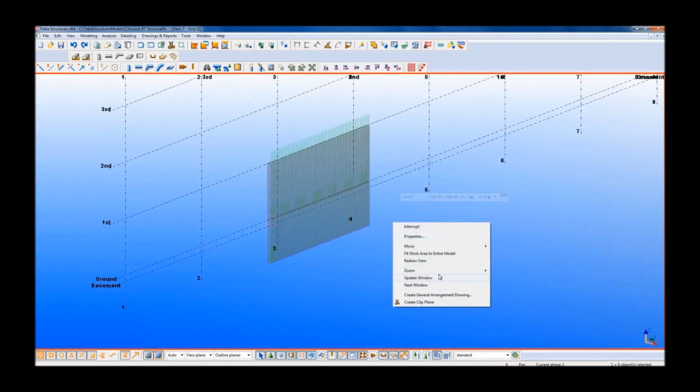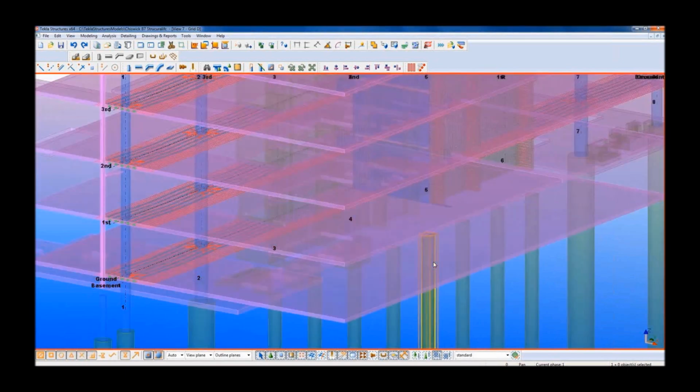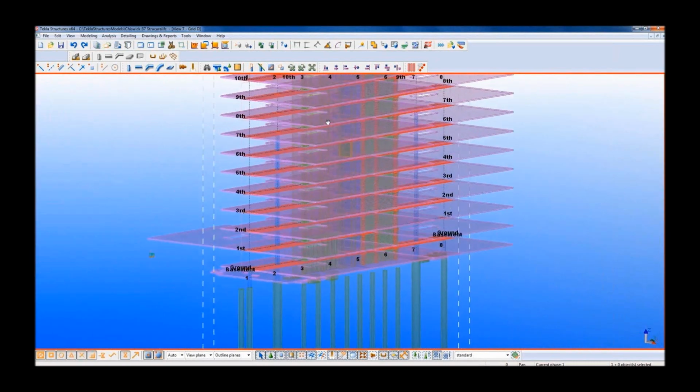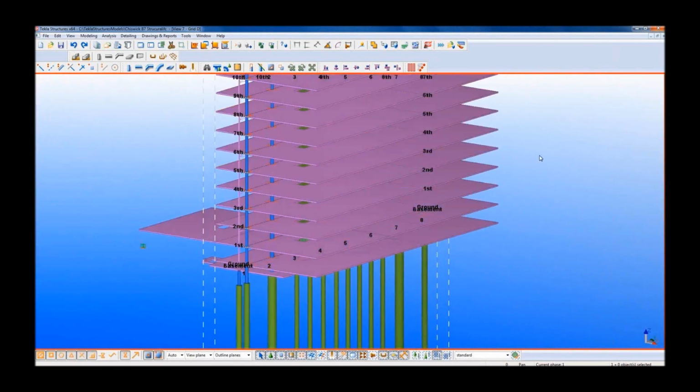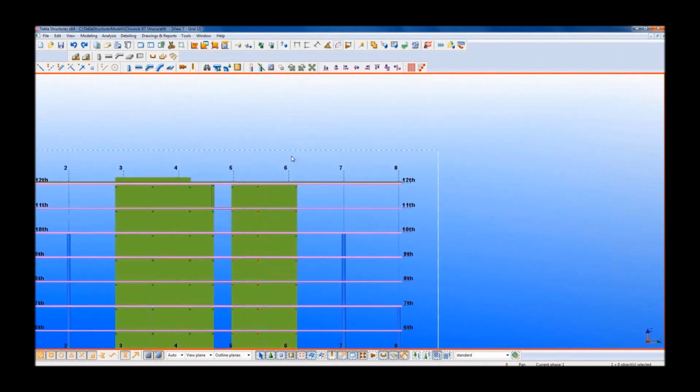So you build up your reinforcement, start to copy it around, and build up the model as you would. It forces good detailing, because you have to think about how they're going to put this together on site. You can't avoid any tricky details. There's no "oh, they'll sort this on site" kind of attitude. It forces good detailing, and obviously it's all going to fit when you get to site.